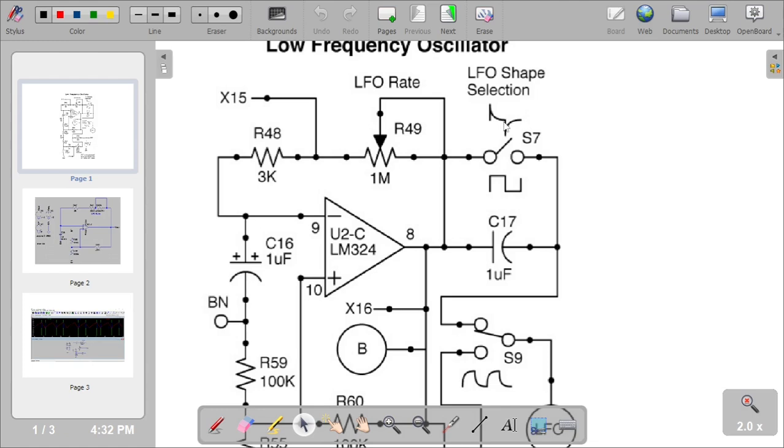So how do you get this thing? Well, you differentiate the square wave, and this is obtained taking the output, that is the square wave, and passing it through a capacitor. So it's super simple. So square wave, capacitor, and you get this.